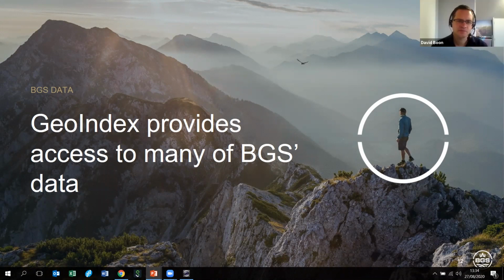And I just wanted to press a point home that we've also got a Geology of Britain viewer, which is a similar sort of thing that a lot of people use, another web tool, but that's very much designed for people to have a very quick look at the geology, more for holiday geologists, I would say, because it's only got some very basic layers on it. So it's got the bedrock geology, the superficial, but it doesn't have the artificial or landslide geology, which could be important for your site. It does have the boreholes, but it doesn't have the AGS boreholes.